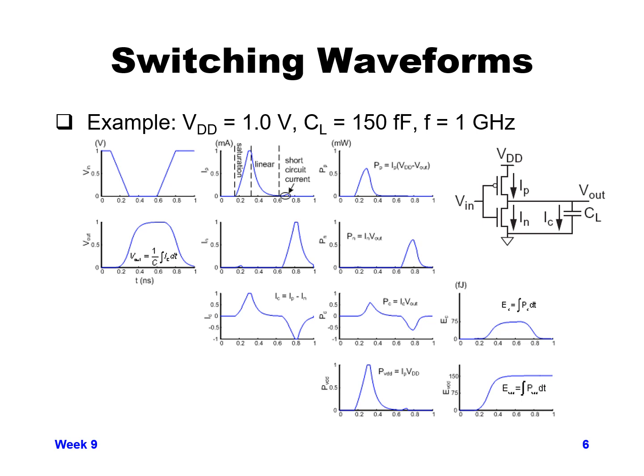Initially it's in saturation, and as VN gets lower and lower, the amount of drive current we have across VGS increases, since our gate voltage is going to 0 and our source is at VDD. As VN gets closer to 0, our VGS is getting larger, and so our saturation current goes up as VGS gets larger.